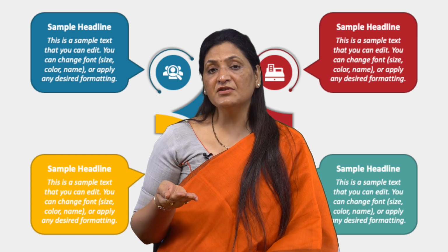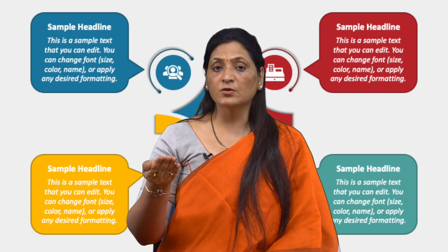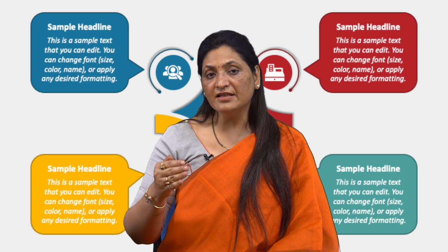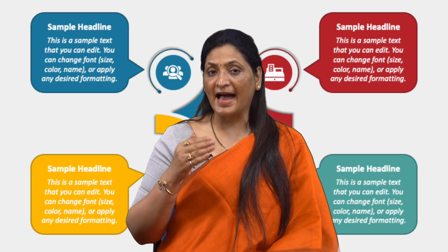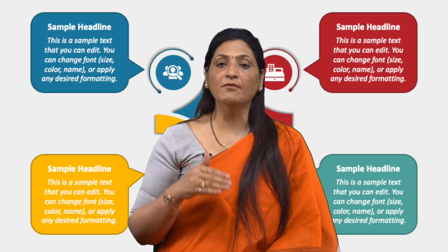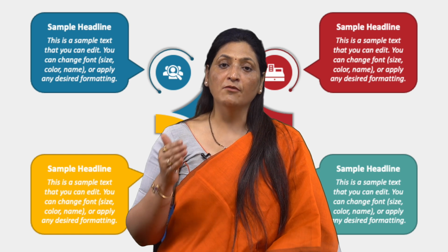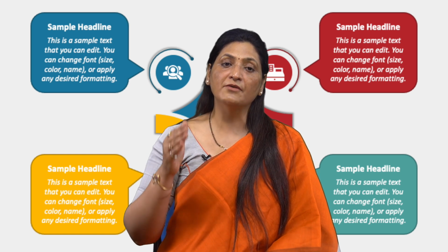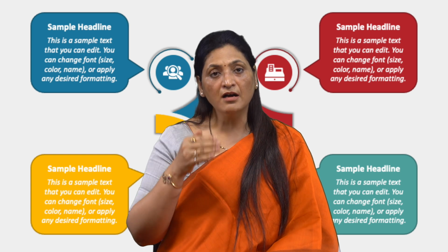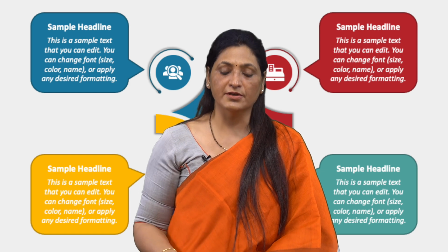In many applications, the motor may be required to run in both directions, as we saw in the case of the bidirectional system. Therefore, in sketching the speed torque characteristics of either the load or the motor, it is preferable to make use of all the four quadrants of the speed torque plane for plotting rather than to confine the characteristics to the first quadrant alone. So, here comes the concept of the four quadrant operation of electric motors.